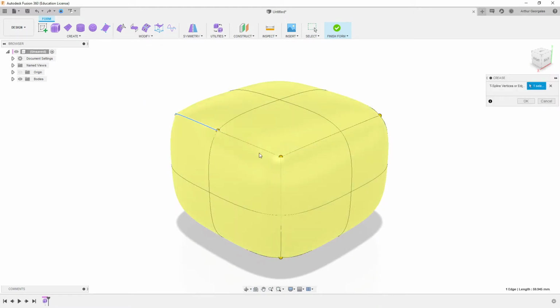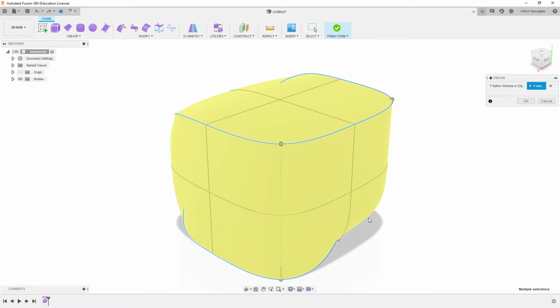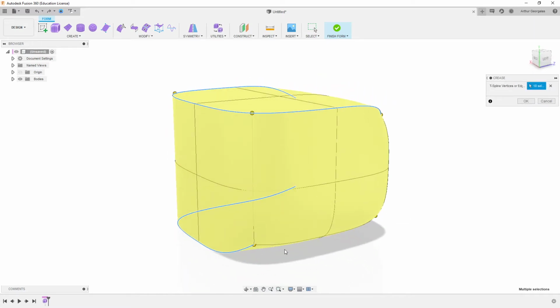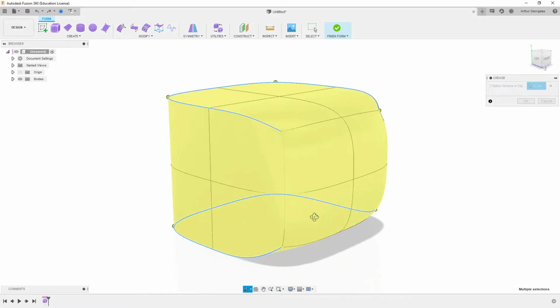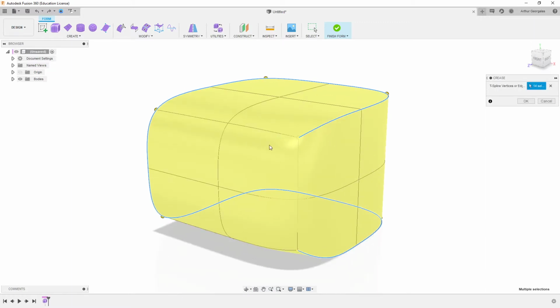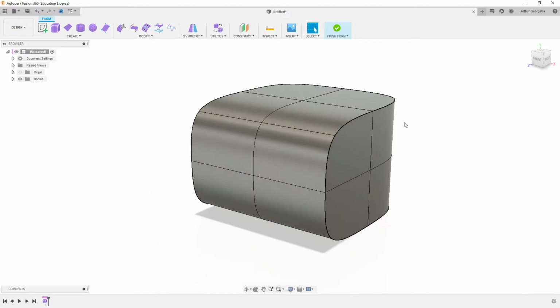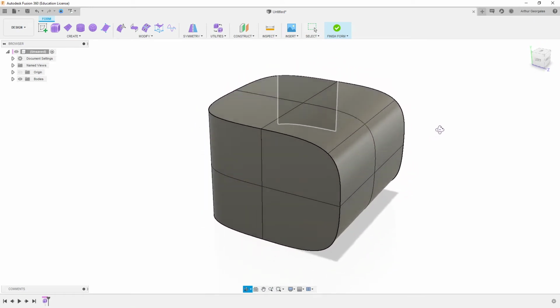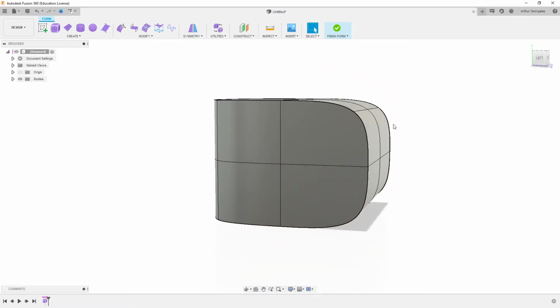I find generally early on in the modeling stage of freeform modeling, I'll use creases more, just because it does get hard to control all these surfaces and edges, and trying to create fillets using freeform surfaces can get a bit out of control, because there's nothing locking it all in place strictly. We don't have dimensions exactly, we're not restraining them and all these things. So I generally try to avoid making fillets like this.